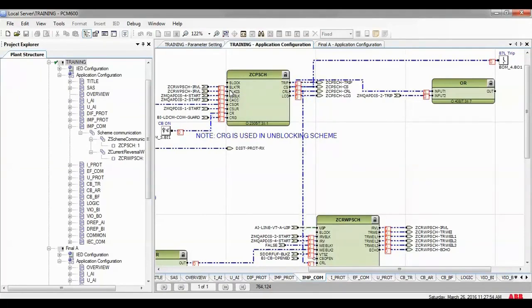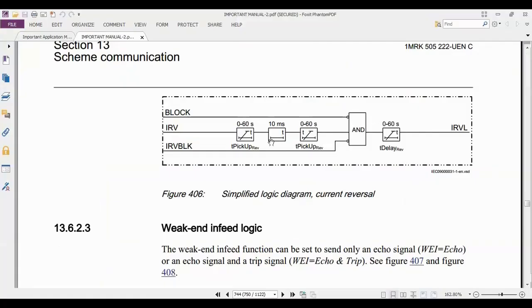Okay, so now we are at this point here. The purpose is that as soon as it sees zone 2, it immediately disconnects. This is not 60, this is 6, and we set it to 200 milliseconds. So it cuts off for 200 milliseconds. If I hadn't connected the zone 2 pickup to this signal, what would have happened is that it would see the zone reverse for 100 milliseconds and then activate.